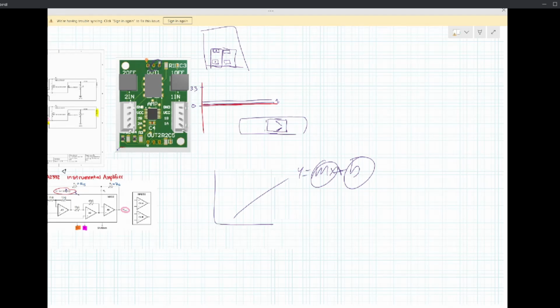For the tie rod and the camber link, where we were measuring axial load, there are two posts in the hatch between the bays, and two really big I-beams that went all the way to the ceiling. And we put a tie rod in between and ratchet straps on either side. And we had a little force meter sitting in line in series with all of this. And we just kept ratcheting until we saw something on the oscilloscope. And then that's how we got our y equals mx plus b equation. It's a little sketchy, but it worked. And I have no doubt that we'll do that again for tie rods and camber links this year, because it worked really well in the end.